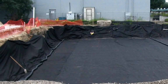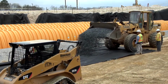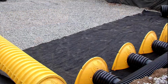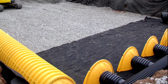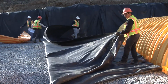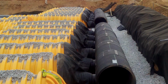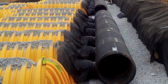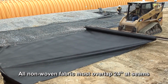Place a non-woven geotextile over the prepared bed and up the walls. Then, place and compact the foundation stone to achieve a flat surface before placing the chambers. A single layer of woven fabric is to be placed on the foundation stone at all inlet rows and the manifold. Use a double layer of woven fabric for the entire length of the isolator row before the chambers are assembled. Non-woven fabric is to be placed on top of the inlet connection and around the entire chamber system, including the manifolds. All non-woven fabric must overlap 24 inches at the seams.